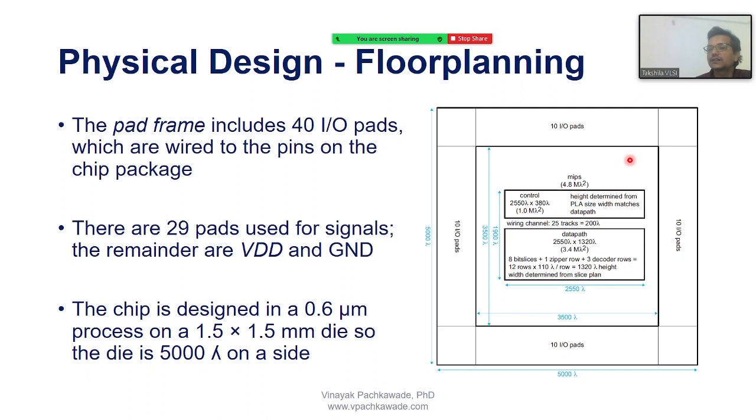Using those inverter cells or cells that you laid out for NAND gate, NOR gate, inverters and tri-states or buffer, you basically call them from your library, or the vendor or manufacturer provides them ready-made in your library, and you place them. You decide as an engineer where to place them to create a bigger logic.